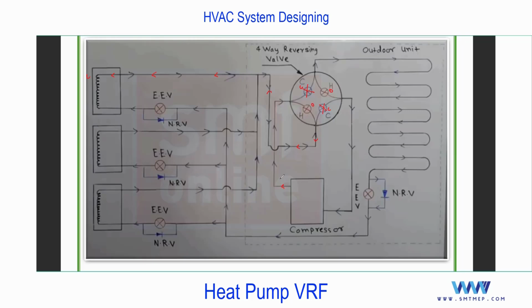Why? Because you see the hot refrigerant with high temperature and pressure entering that heat exchanger means this will become the condenser. And the room temperature is low because we are using it in winter, since I'm talking about the heating mode. When the air is thrown on this, the refrigerant loses heat to the room air and changes phase from vapor to liquid, and at the outlet you'll find the same cycle but reverse. So you'll find the refrigerant in liquid state. Now the refrigerant will not pass through this electronic expansion valve.